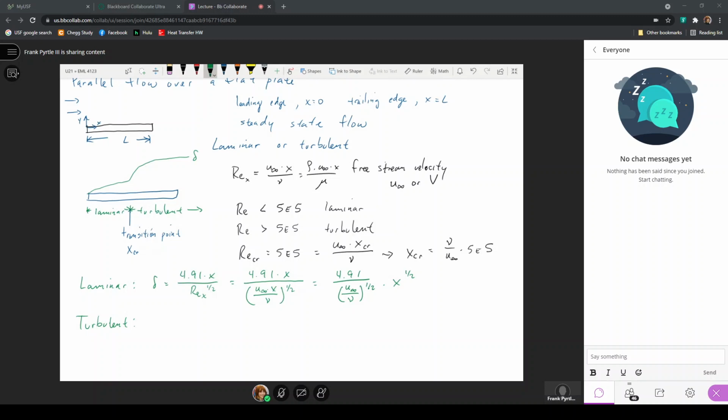In the turbulent flow condition, we still have a laminar sublayer very close to the surface, but everywhere above that laminar sublayer, all the way up into the boundary layer thickness, we have rotation of the fluid. And what that does is it actually enhances heat transfer, but it increases pressure drop associated with the hydrodynamics of the problem.